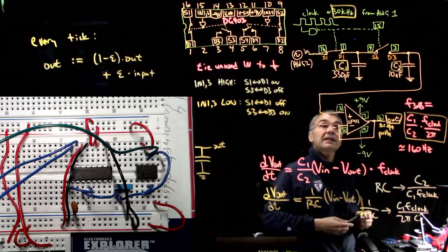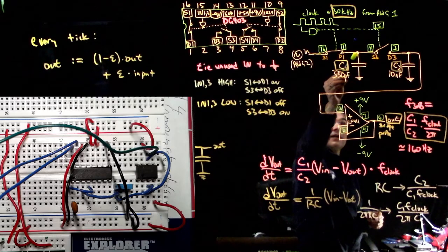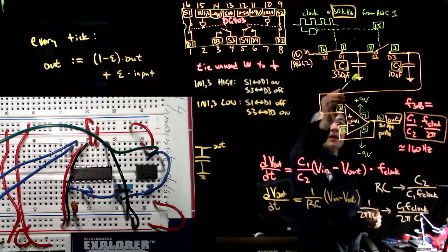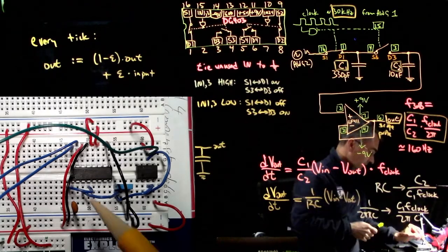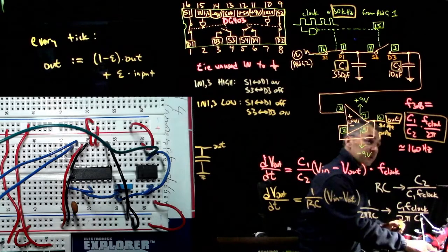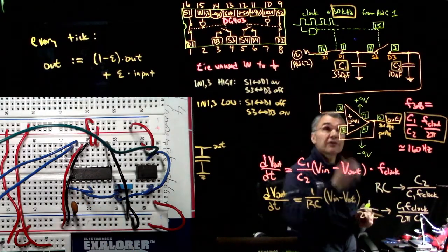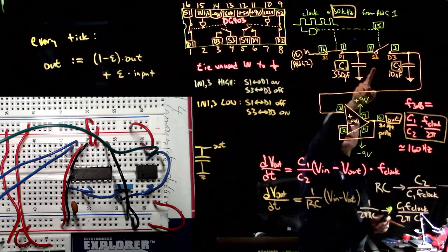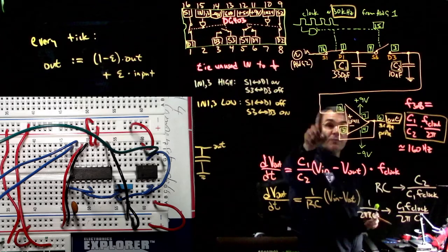Then pin 1 is wired to pin 4, and somewhere between the two there's a capacitor to ground. So pin 1 over here with this little blue wire is wired to pin 4, and then I have this capacitor to ground, which is a 330 pF capacitor. Then pin 3 goes to pin 3 of the op amp.